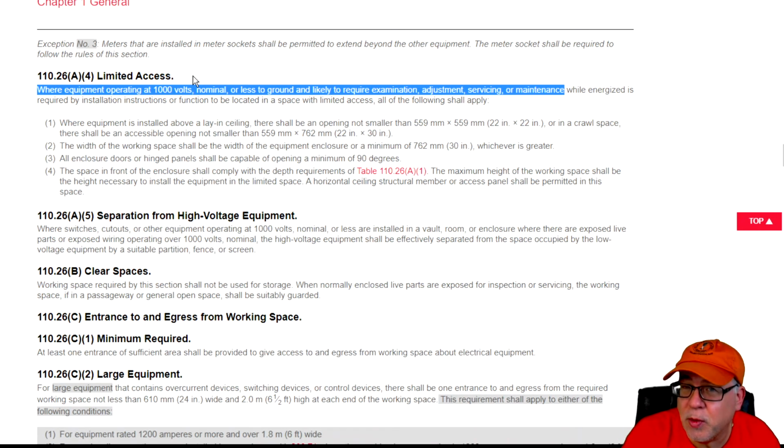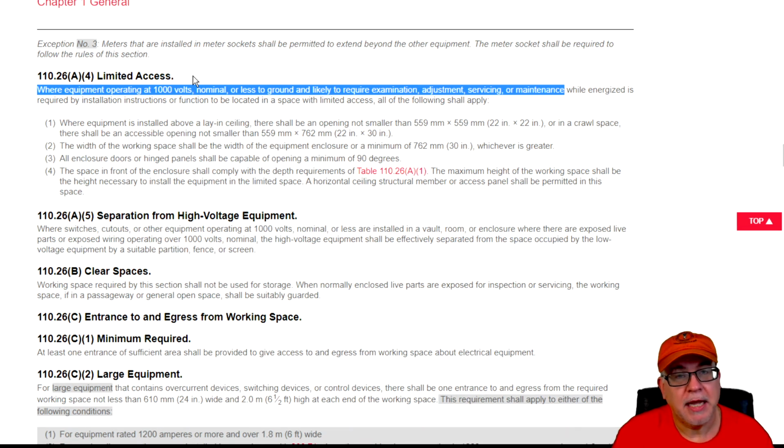Do you need to do it while it's energized? That's the trigger, okay? Air conditioning unit, I'm checking for voltage. Obviously, I've got to do that while it's energized, okay? For a transformer, do I necessarily need to do that while it's energized when I can always go to the first disconnect and test it there? That type of thing. Now, when I'm servicing an air conditioning unit, I need to test certain things while it's energized. You with me? So it's different ways to put these little things in a basket.